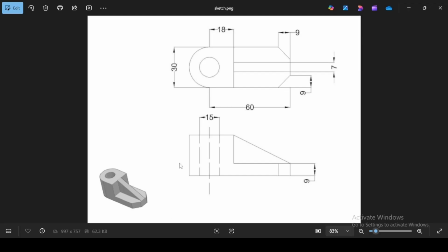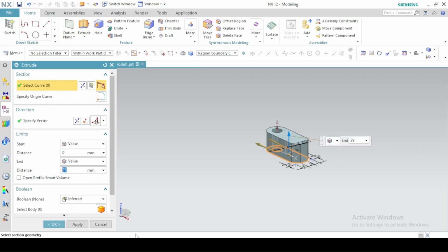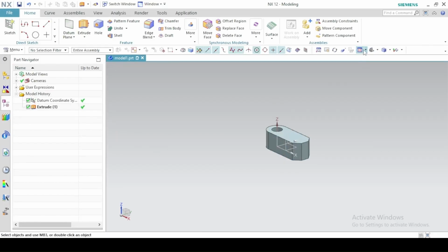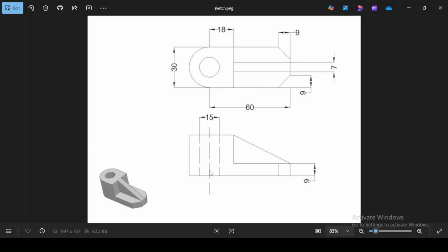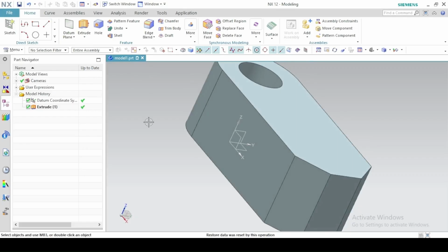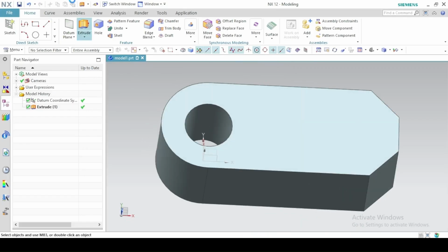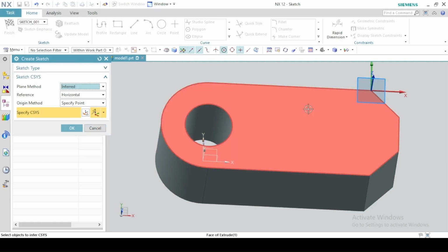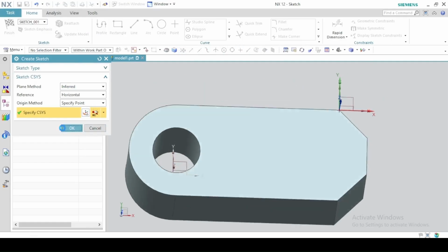And we extrude up by 25 millimeters. Click OK. Next, we'll cut this side from it, which is over here. And we cut down by a distance of the 25 millimeters minus the 9 millimeters over here, which will give us 16 millimeters. So first, rotate the drawing and then click on the extrude feature, come to sketch section and click on this face here and click OK.